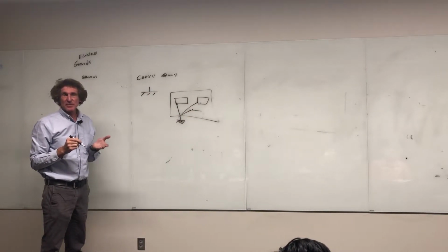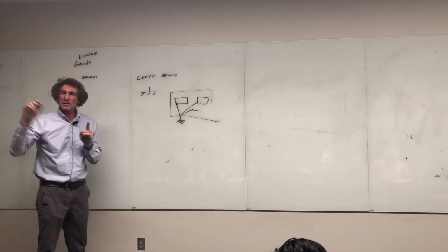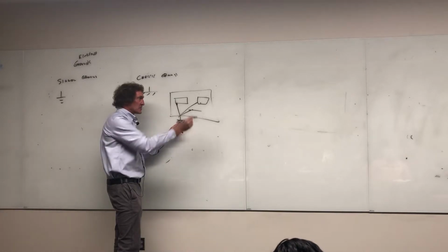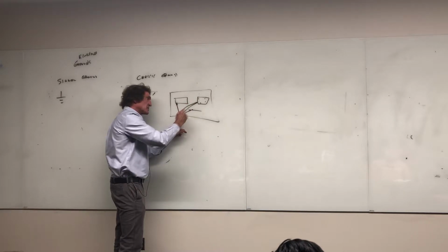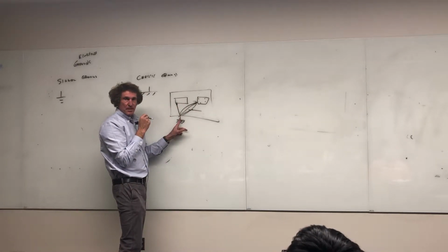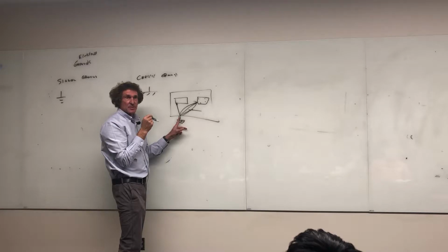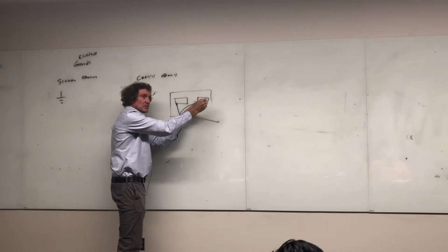Now, the chassis ground is something you've got to be aware of for one reason. When you're measuring signals that are 100 kilohertz or higher, or clock cycles, if I use this ground and start measuring voltages on this chip, I may get an error because this will develop an impedance. And that impedance will cause a voltage difference that you don't want. If you're going to make accurate measurements on individual boards inside a chassis, you've got to put your negative lead on the ground on that board and then do the measurements.